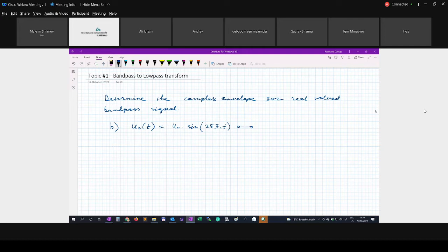If you have a real spectrum, it means this spectrum is represented by a cosine component at some frequency. But if you have an imaginary component in your spectrum, it means it's represented by a cosine wave shifted by 90 degrees, or just by sine. But it's absolutely fine. You can, of course, implement it without any problems.